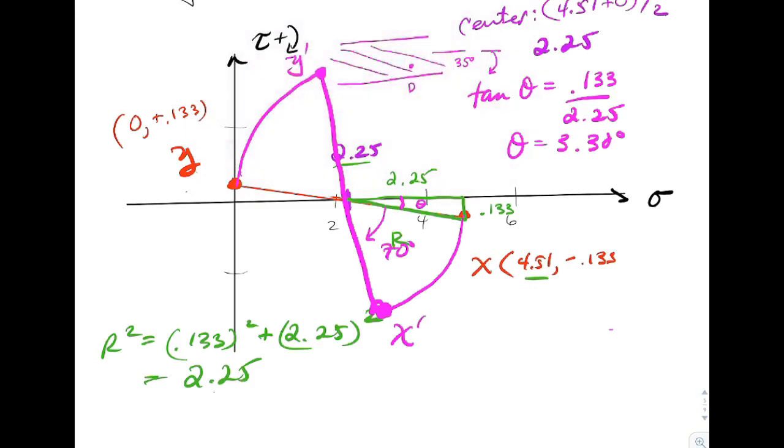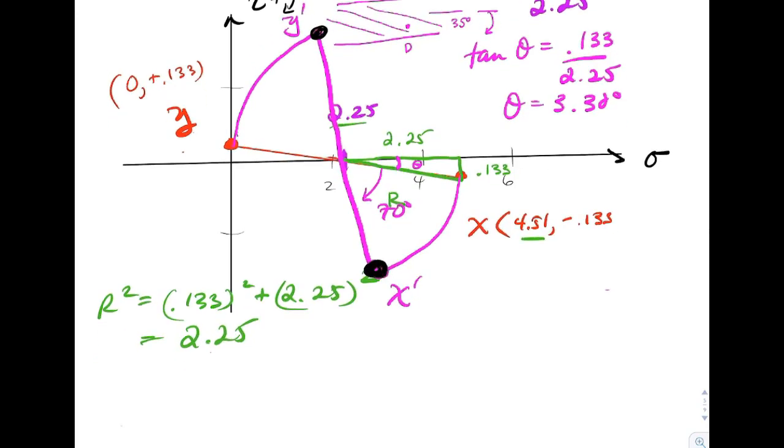So what we need are the coordinates of those points. The coordinates of those points will give us the stress at the rotated amount. So let's go ahead and highlight a triangle right here. That triangle right there. So up here, this will be L1. That'll be L2. So I'm just going to redraw this triangle down here. There's L1. There's L2. That's a 90 degrees.